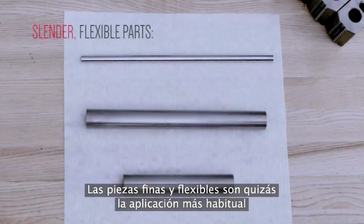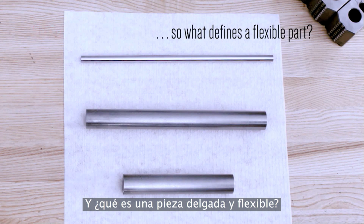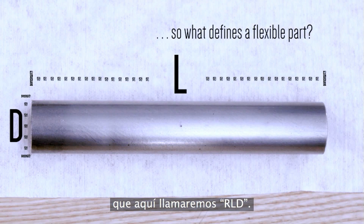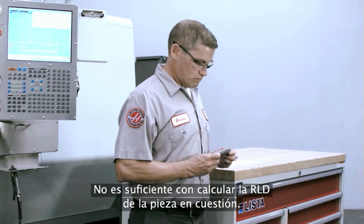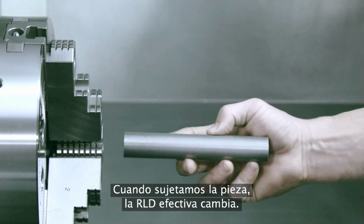Slender, flexible parts are probably the most common application where tailstock support is required. So what defines a slender, flexible part? The most common way is to refer to its length to diameter ratio, or L to D as it's often referred to. But let's be more specific. It really isn't enough just to look at the L to D ratio of the part by itself. When we grip the part, the effective L to D ratio changes.